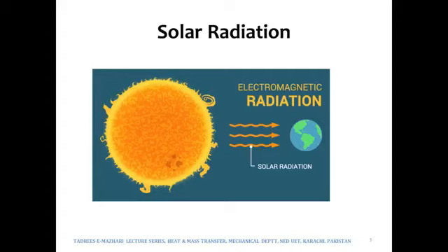That is related to its temperature, as discussed before, because E is sigma T^4 or sigma epsilon T^4. So emissive power is directly related to the temperature of the body. The higher the temperature of the body, the more radiation would be emitted out of it, meaning more would be its emissive power. And E over here has units of watts per meter square. All those things have been discussed in chapter number 1. So kindly go over that stuff before you start chapter number 12.